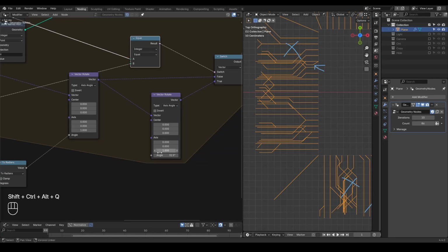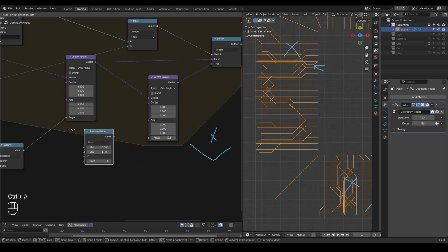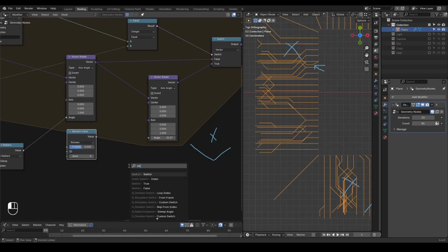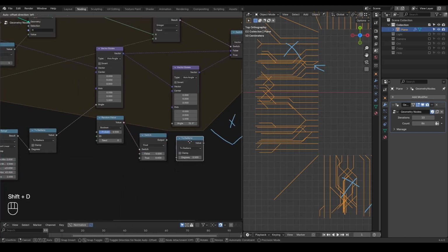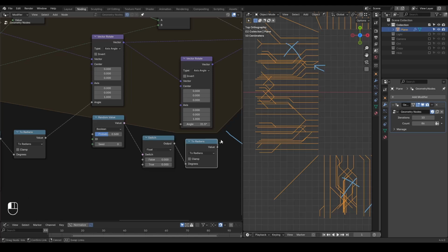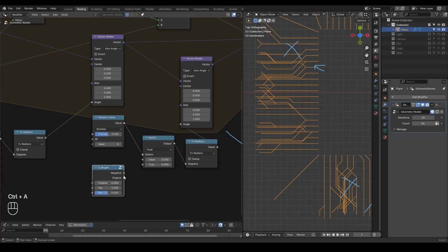Next, we just need to generate a random value and the conditions to determine if it's going to the left or right. Of course, we do not allow it to go in the straightforward direction, otherwise it will cause the overlap again. So here I'm just going to use a random value node again, put that into the boolean, take a switch. I'm going to switch with the float, using 2 radians so that I can input the degrees of false and true. I'm going to use a negative so that I can output a positive value and a negative value accordingly. And then put that into 45 degrees.